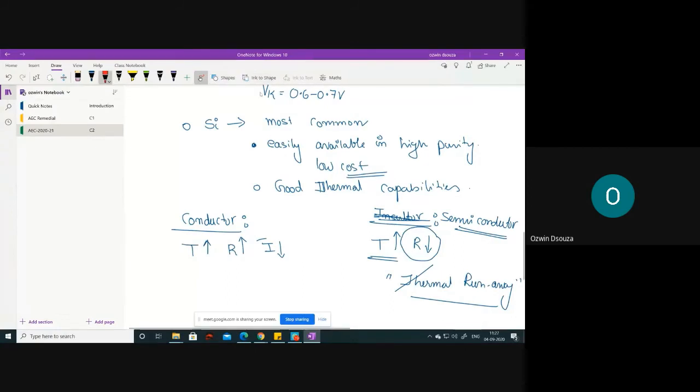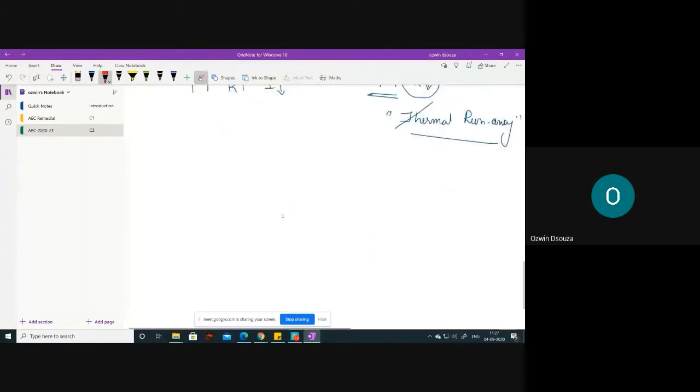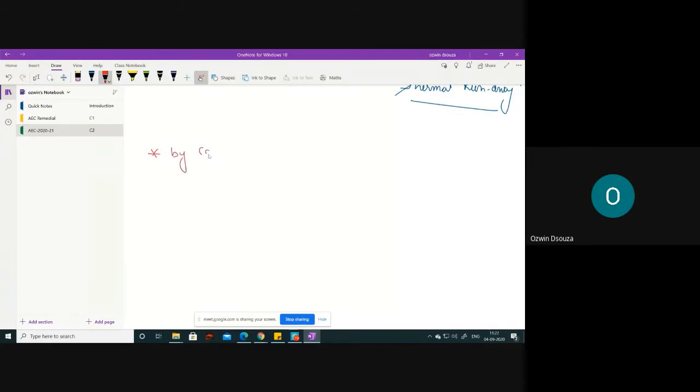So the summary of our discussion is that you are supposed to consider the barrier potential while constructing the equivalent circuit. Now let us construct the equivalent circuit by considering RD, that is the dynamic resistance of the diode, and also the barrier potential Vk. Let us use these two elements in our equivalent circuit.